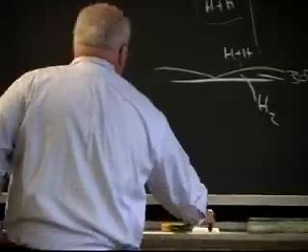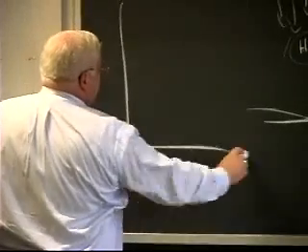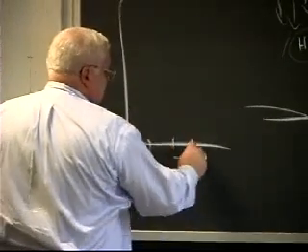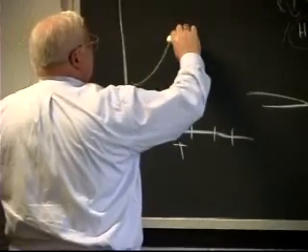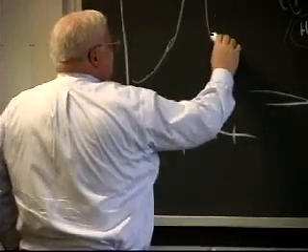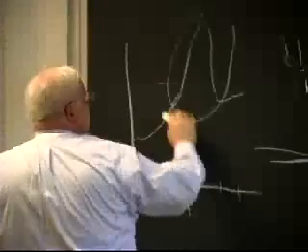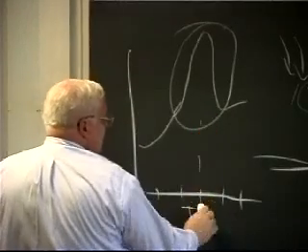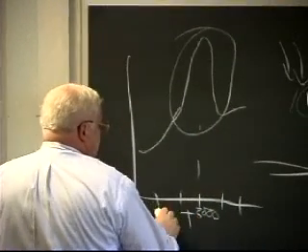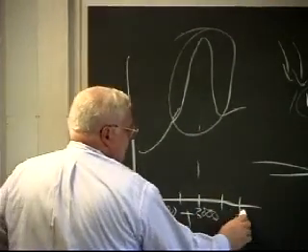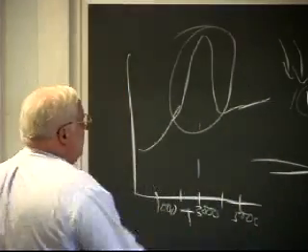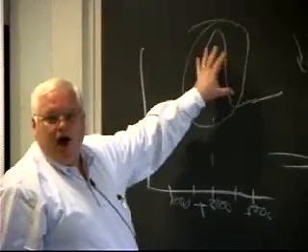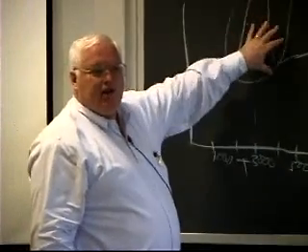And so if you plot the thermal conductivity versus temperature of a diatomic gas, and we're talking in thousands of degrees Kelvin, you'll find some kind of plot that looks like that, okay? This is the temperature range, maybe 3,000 Kelvin, if this is thousands of Kelvin. Up here, I'm monatomic. Down here, I'm diatomic. And in here, I'm reacting and carrying the heat of dissociation.